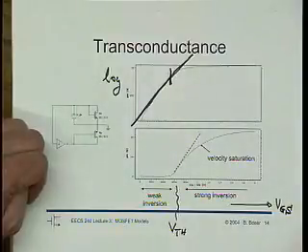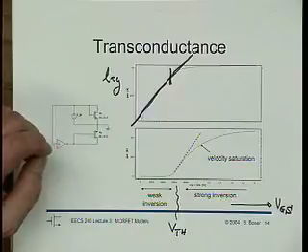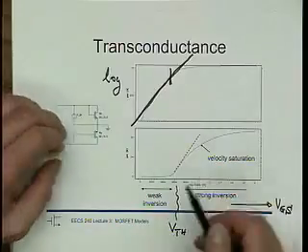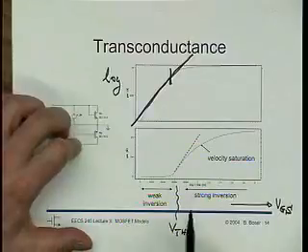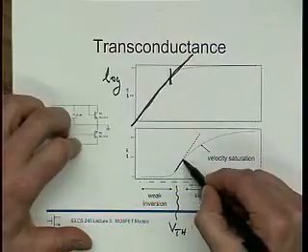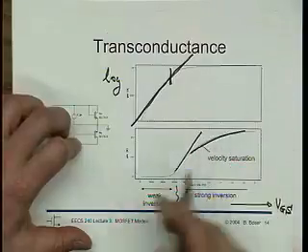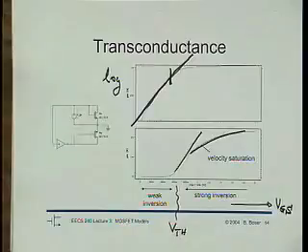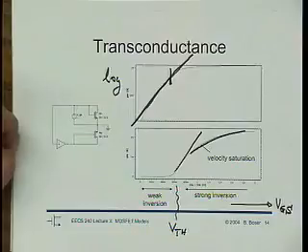Then for values of VGS that are larger than VTH, my transconductance should increase proportional to VGS, so that would be this line here. But in reality, it bends over quite significantly, and the reason is short channel effects like velocity saturation, also vertical field, and so on.